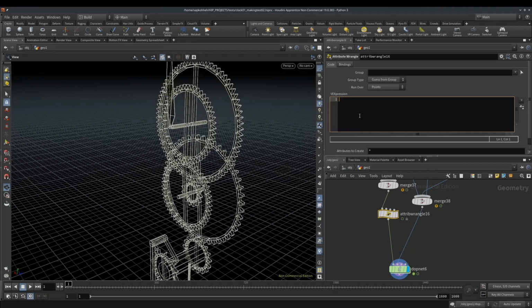Unfortunately, Bullet, at least Bullet in Houdini, is a bit stupid. If A is not allowed to collide with B, it thinks that B is still allowed to collide with A. So we need to make it understand that it's bad both ways. So for collision group arrows, we will set collision ignore to be base and arrows, so it doesn't collide with either of them.